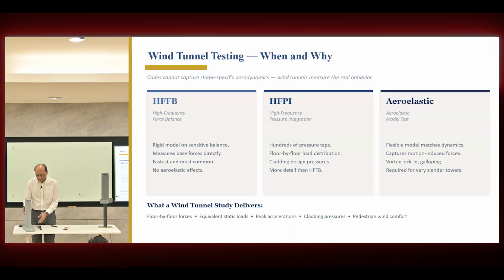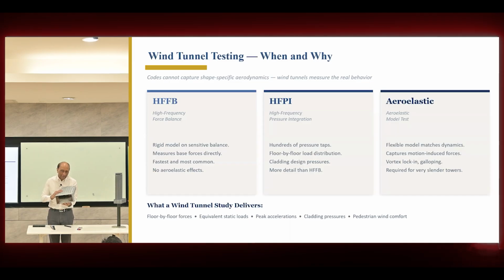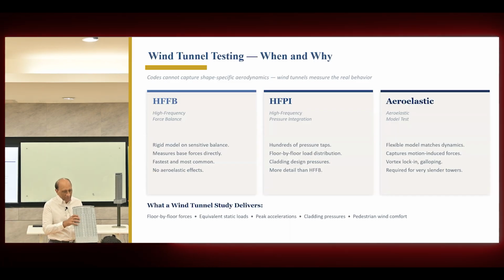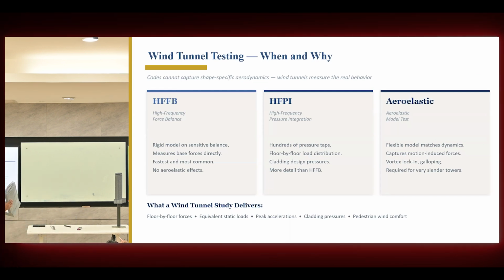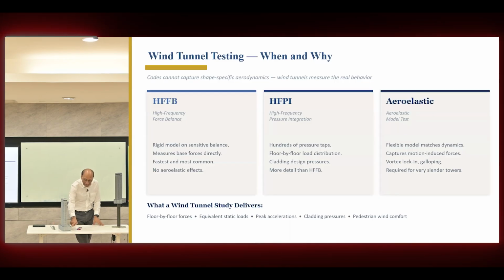Then the second model is the high frequency pressure integration. If you look inside, you will see that there are hundreds of pressure taps. If you look closely, there are small holes on the model. Each hole is wired to a tap, and these are actually very small tubes, going down and connected. And then the pressure will be measured at every location on the surface, and especially at this location,